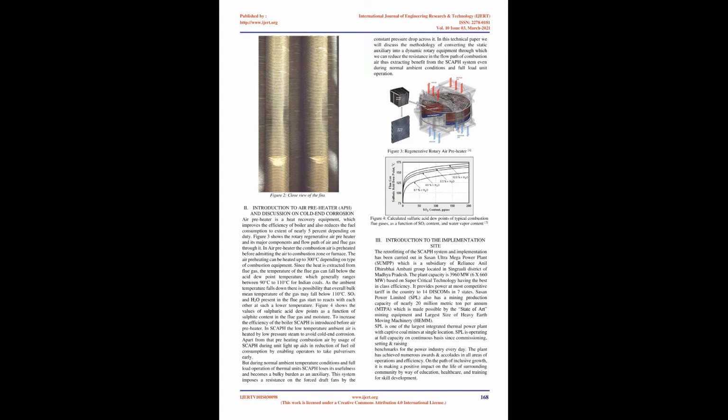Steam flows inside the tube while air passes over the fin tubes. It is generally used for heating process air or combustion air. SCAF has extensive uses in all high-capacity boilers and recovery boilers. Steam coil preheater is used to heat inlet air to the air preheater, APH, in order to raise the cold end temperature, thus preventing acid dew point corrosion.